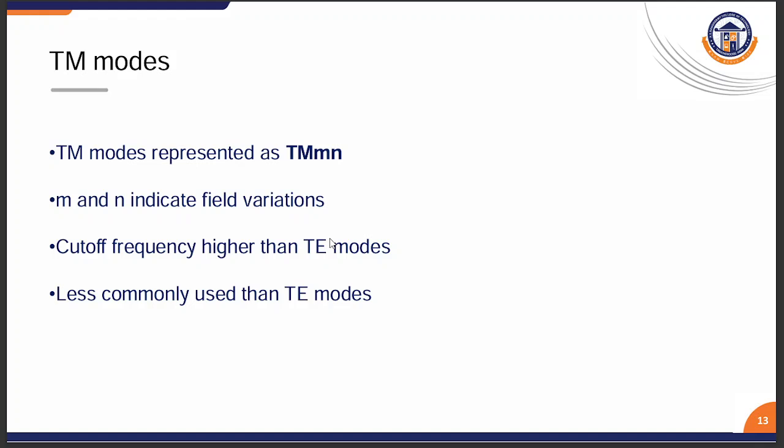However, the TM00 mode does not exist because such a configuration cannot satisfy the boundary condition of the waveguide. So TM modes always exhibit cutoff frequencies, and these cutoff frequencies are generally higher than those of the TE modes for the same waveguide dimension. So this makes TM modes less commonly used in practice compared to the dominant TE mode.